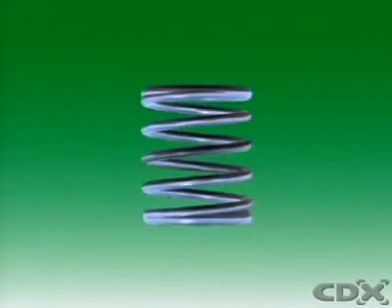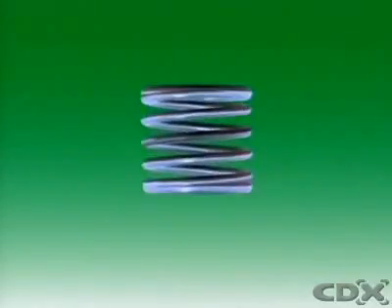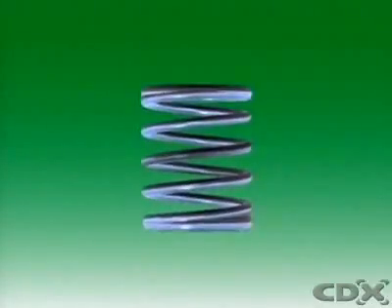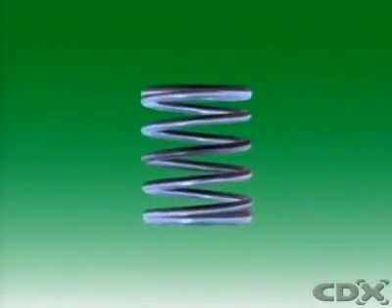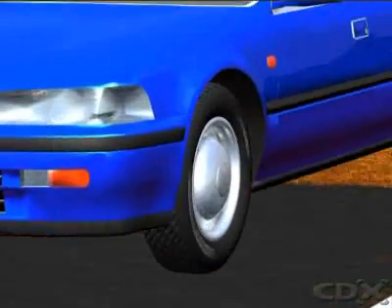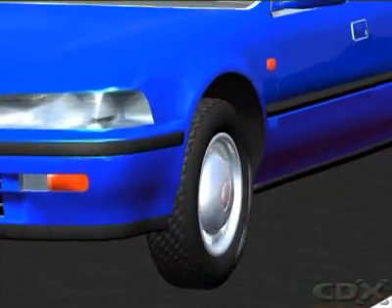When a vehicle strikes an uneven surface, the springs are deformed from their original shape. They return to their original position, but tend to overshoot and set up oscillations. This makes the vehicle bounce up and down, which makes the ride uncomfortable. It can produce forces that make the tyres bounce, and a bouncing tyre won't grip the road surface well.